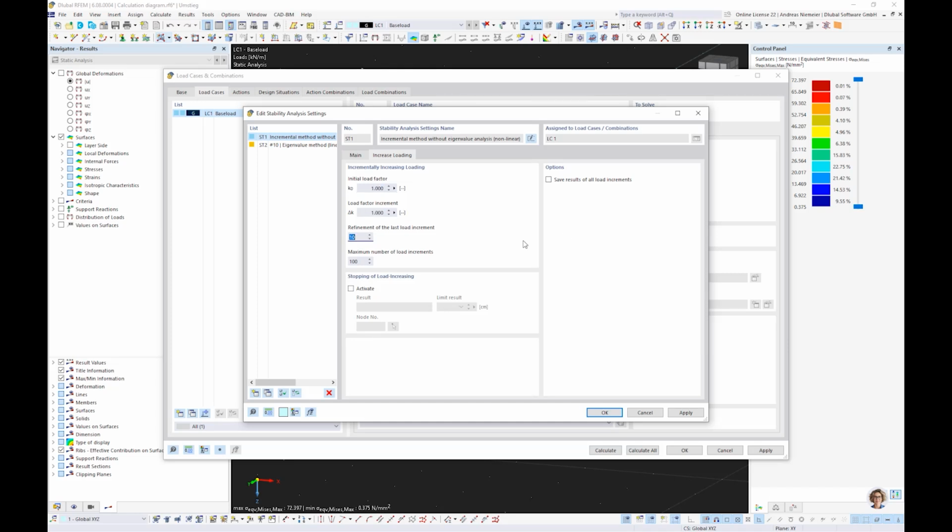Refinement should be done with 5 in the last step, and we want to have maybe 10 increments. Because it makes no sense to calculate deflections from here to the moon, let's stop at 15 centimeters max. And because this could be one process that gives me a load increasing factor, but I want to look inside this calculation, I save the results of all steps.